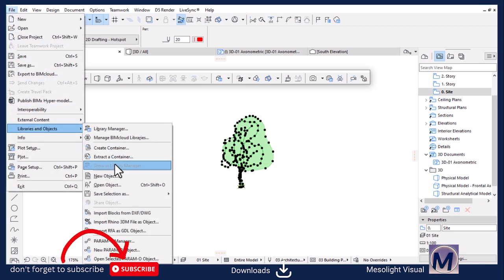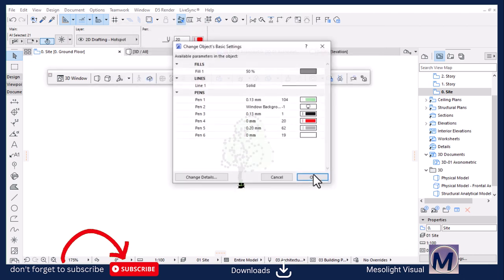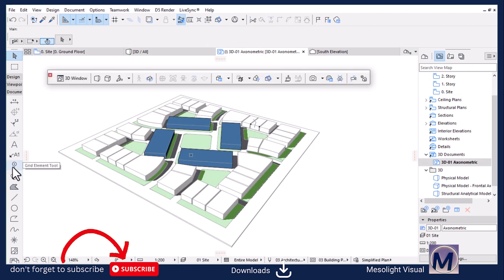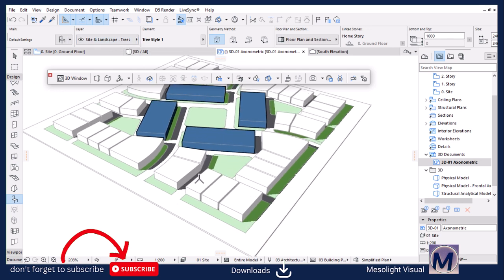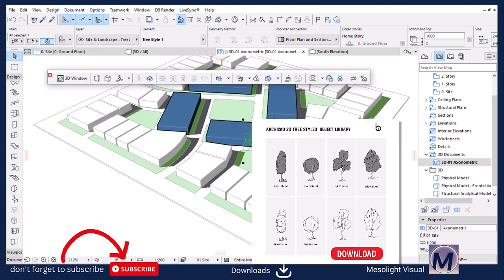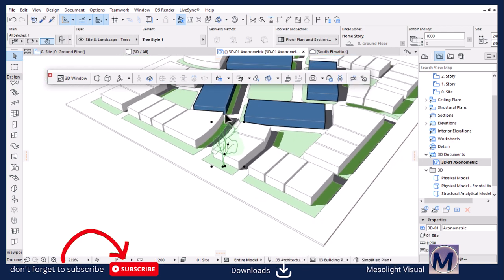Go to File, Libraries and Objects. Let's save selection as an object. So you can create a folder there and make your own library. Then I'll call it tree style 1. Then hit OK. So if you go back to the axonometric view, let's activate the object tool, make sure it's under trees, and then let's place it here, then move it to there. Let me move it somewhere here so that you can see the difference.